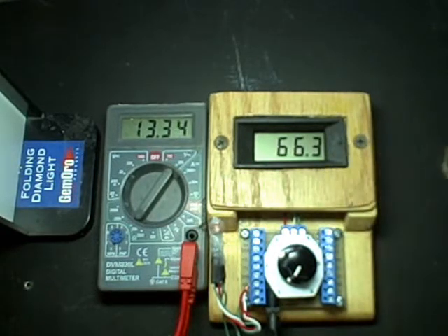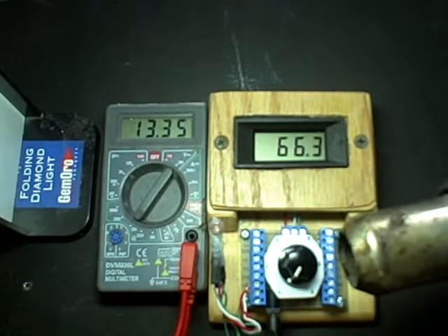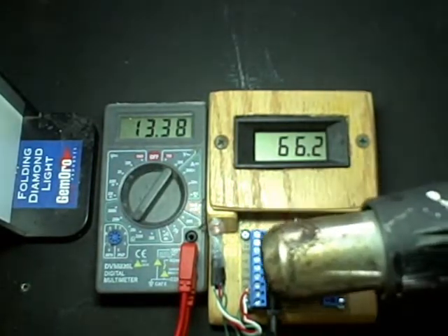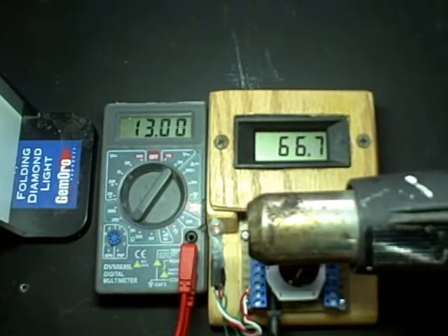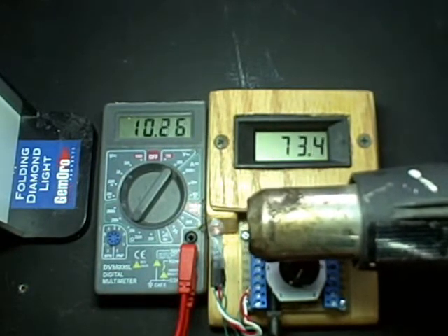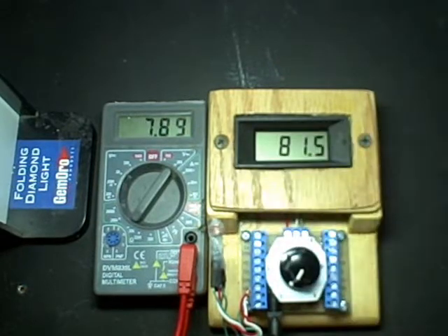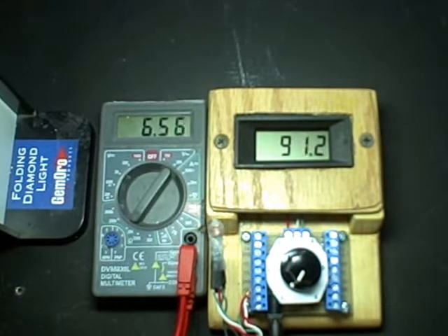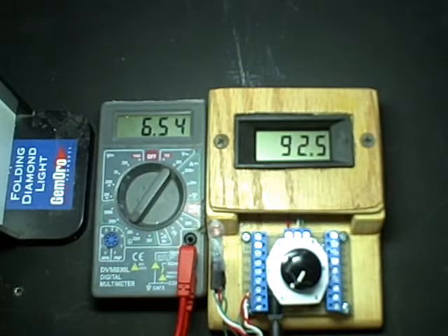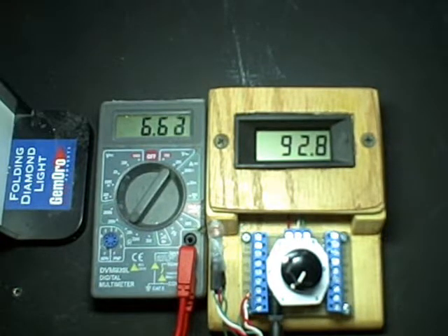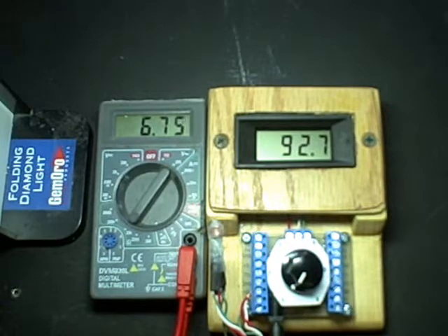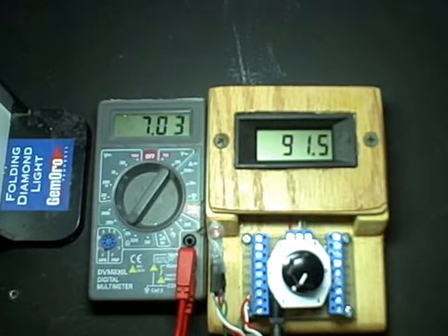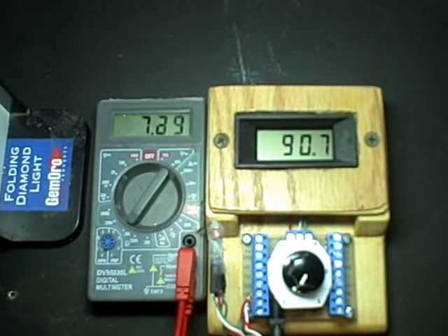Now let's add a little heat. I have this heat gun here. We'll add some heat and watch what happens to the resistance of the thermistor. You can see the temperature is just starting to change. 66, 67, 73. Now look at the resistance already. Took the heat gun away. See, the resistance went way down. Now it's about 6.5 kiloohms, and the temperature is 92 degrees. Okay, we'll let that equalize a little bit so you can see. So it's probably just about 7K at 90 degrees Fahrenheit.